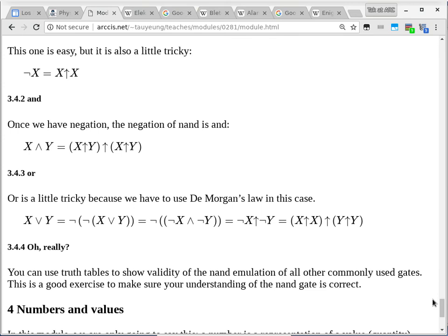The negation of X or Y can be rewritten as not x and not y. That's the part where it gets a little bit tricky because it's not obvious. So what happens when you look at something like this and you're not 100% convinced that this portion is really the same thing as this portion here? This is, by the way, called De Morgan's law. But what if you're not convinced that De Morgan is right?